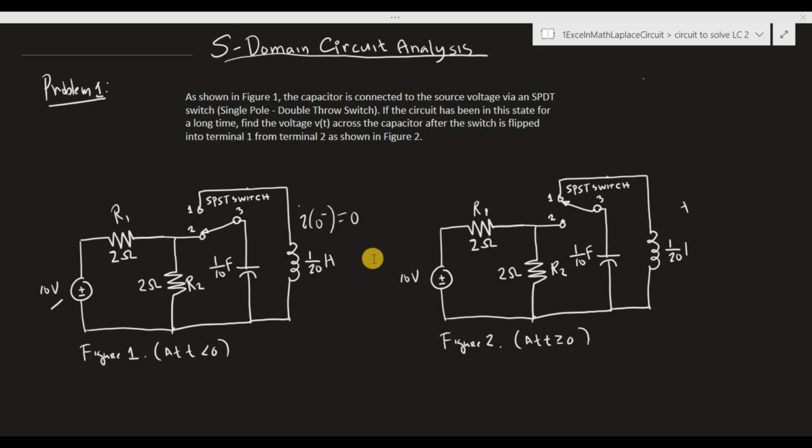In the S domain, capacitors and inductors are treated as if they were just resistors, and therefore we can directly apply Ohm's law and other circuit analysis techniques that we know to solve the equivalent circuit in the S domain. Instead of applying calculus, we can just solve the circuit algebraically. And after finding the solution, we can apply the inverse Laplace transform to obtain the final solution in the time domain.